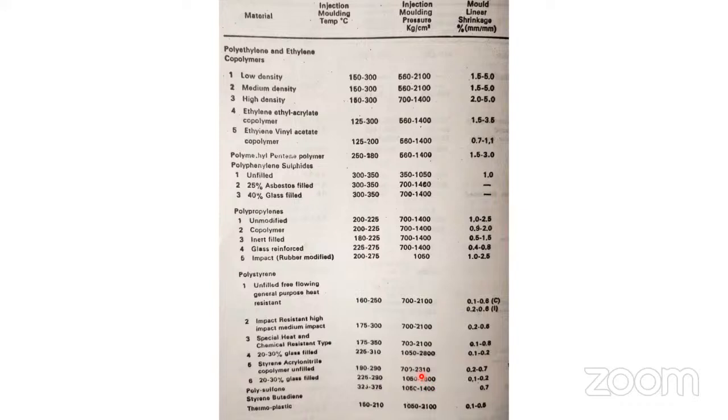It increases the tensile strength. Okay. But I have never seen ABS with GF added. If the strength increases, the dimensional stability will increase. Maybe ABS material is costlier, that's why people prefer PP plus GF. No, it might not be the reason. Some people want it for some applications. If it is a strength requirement, then PP plus GF compared to ABS will be cheaper.